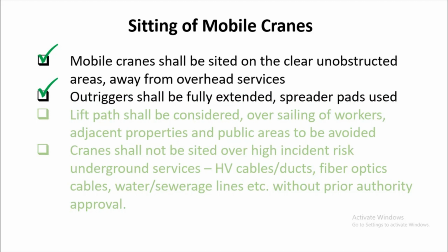Outriggers shall be fully extended. Spreader pads shall be used. So make sure that the outriggers of the mobile cranes are fully extended, because this will gain stability for the mobile cranes. So it is very important that the outrigger is fully extended.